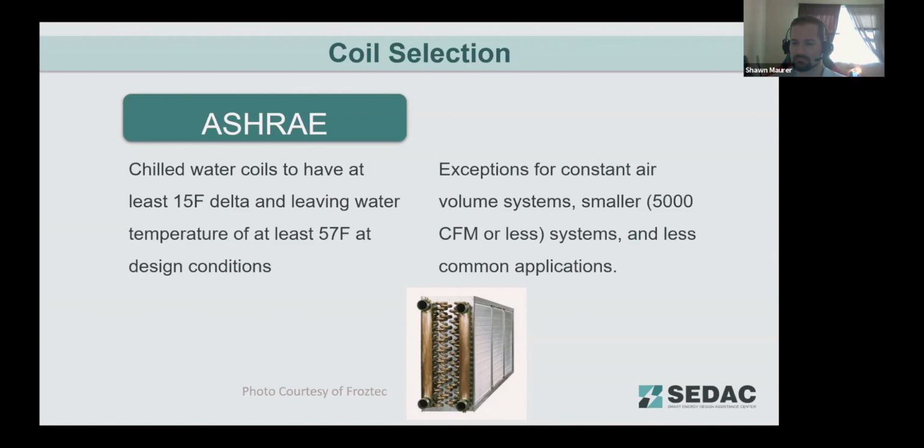You also reduce the chance that the low delta T coming back to the chiller limits that chiller's output. So on top of the efficiency decrease from having colder water come back to the chiller, it can also limit the capacity of that system. Again, we're looking for these minor things we don't necessarily always think about that have a pretty large impact on overall plant efficiency and operation. Something to be aware of: most chillers have a capacity based on a 10-degree differential between the supply and return.